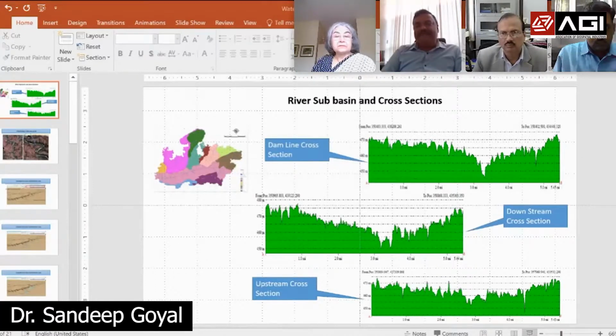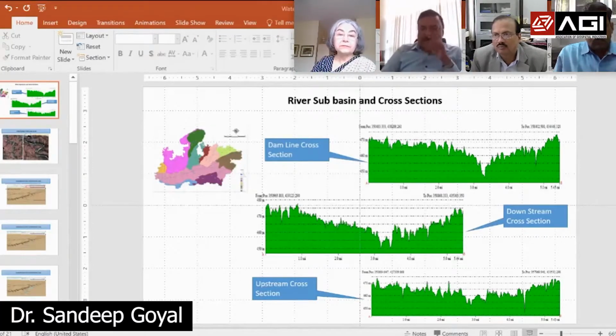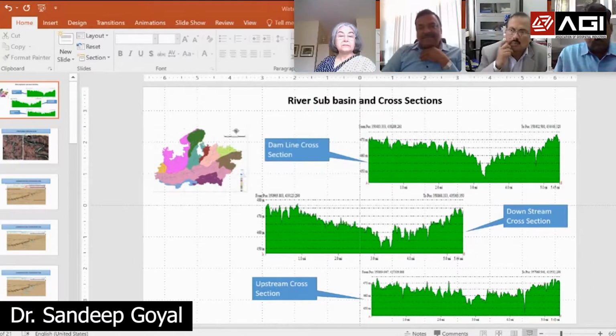And this is the recent one which we have done with the help of drone survey. Our own drone unit is there. We conducted the 3D survey. These are some sample images of the said area. This was the proposed structure which was supposed to be constructed, and the DPR is already in process. We surveyed it, and we showed that at the selected site there are some micro lineaments which are not visible by other means. Those can be picked up in a drone survey, and you can see that we have gone on different levels here, and then we also provided a digital surface model to WRD.